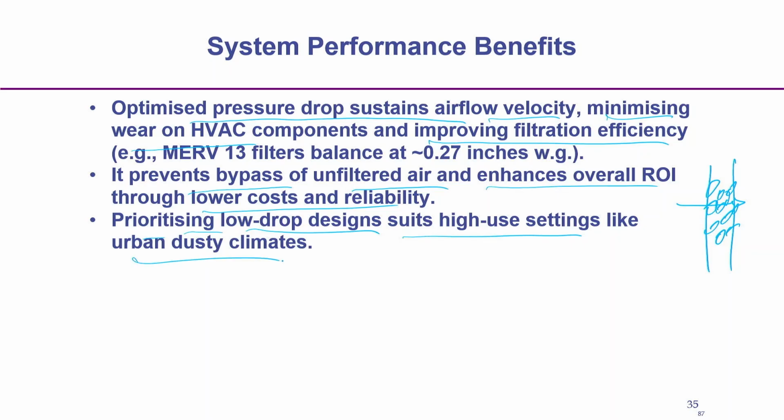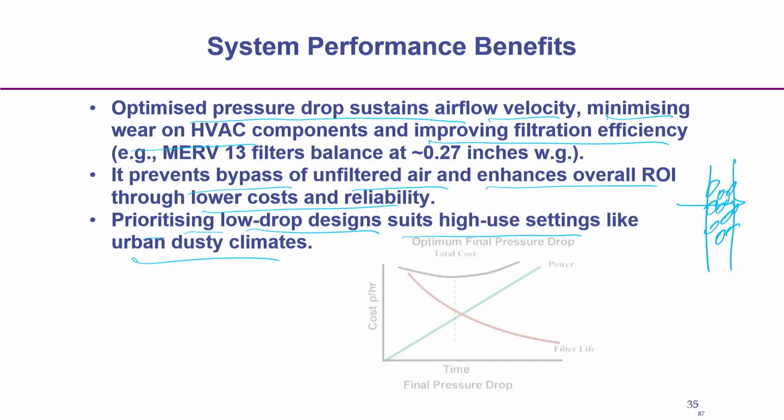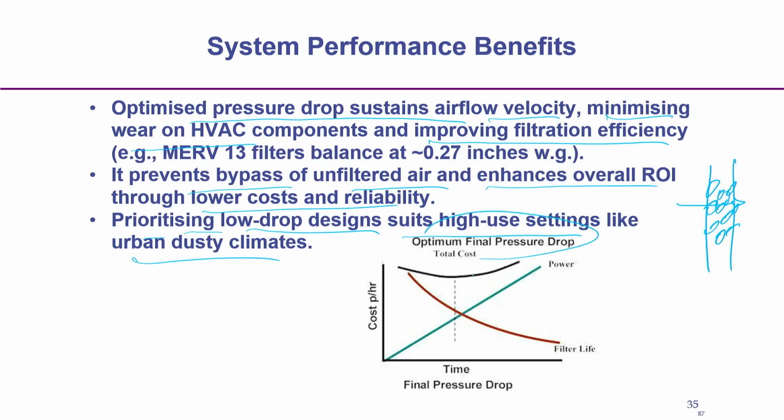Where a dusty climate is there, we should use a filter medium with a lower pressure drop. So, the optimum final pressure drop is here, where we can have a certain amount of pressure drop to optimize.